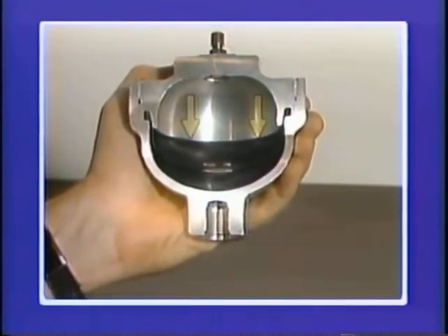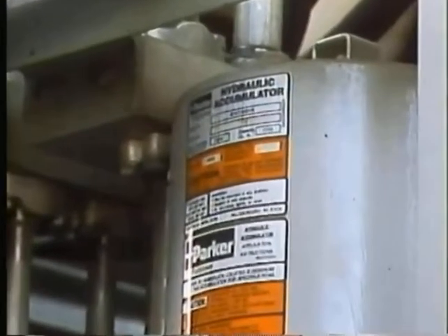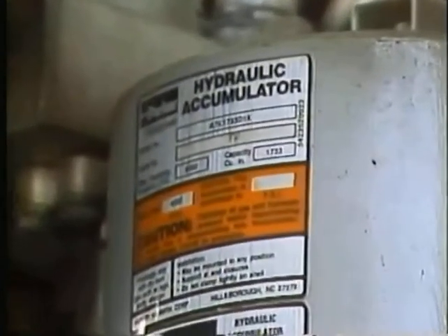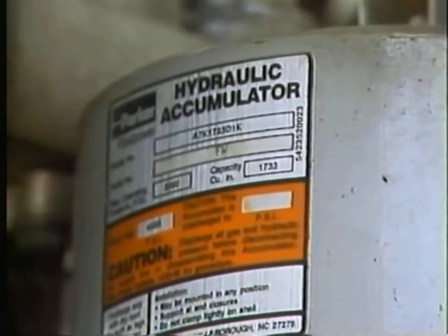When additional fluid is needed in the system, the gas pushes against the bladder and forces the fluid into the system. To work properly and avoid damage, these accumulators, like the one we just saw, have to be properly charged with gas. Operators should follow their procedures for the method and frequency of checking the gas pressure on this type of accumulator. The checks we've talked about aren't the only ones you might have to make on the hydraulic systems in your facility. You can refer to your operating procedures or supervisor to find out exactly what your responsibilities are.